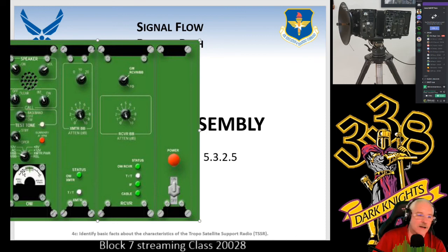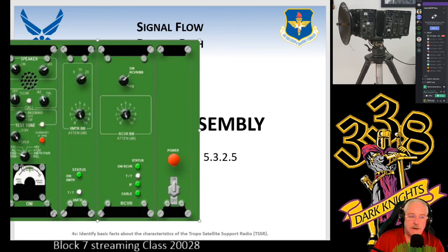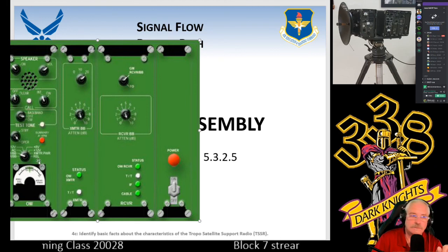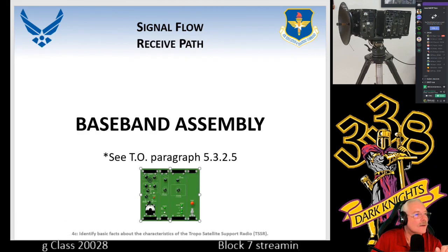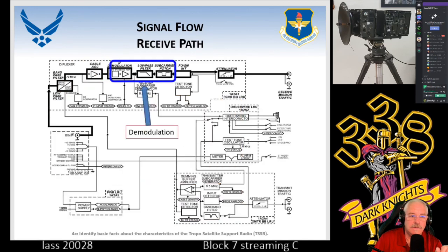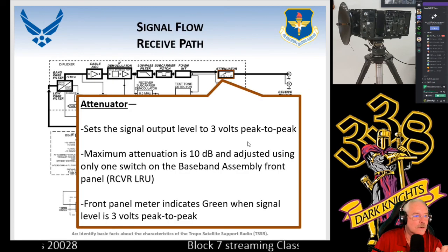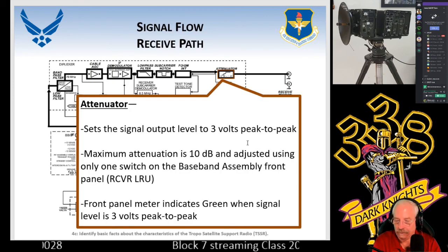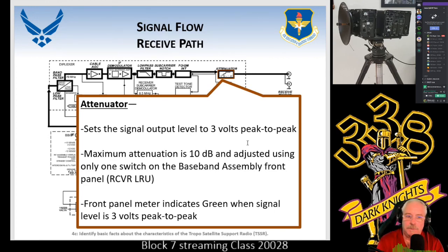So that's the selection switch. Same for the transmit baseband. If it's really strong, you got to use the meter. It's got to be in that transmitter baseband selection right here on the left-hand side, and then you adjust its attenuator to where it is in the green. Now, I can tell you, when you are doing your setups, we have no multiplexer.